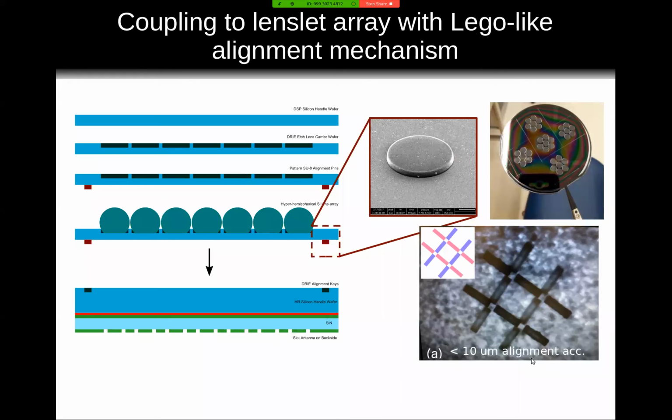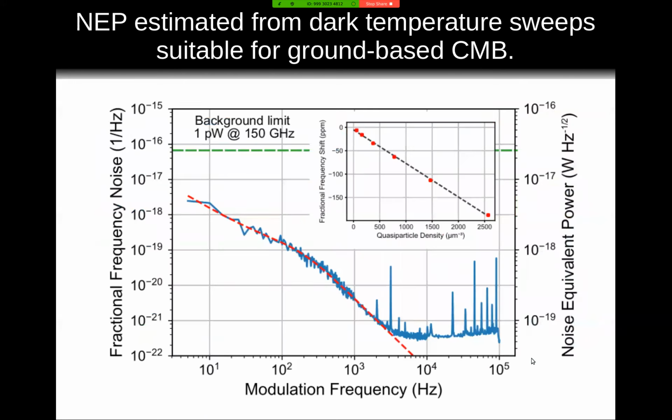The other question is, how well can you actually measure noise, or is your detector sensitive enough to make the measurement you want? This is a very weird unit that's used in the MKID world, fractional frequency noise, which is measured in 1/root hertz. So it's the square of hertz over hertz squared, which is kind of strange.